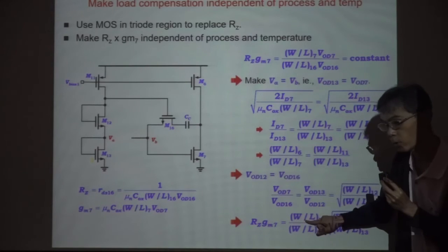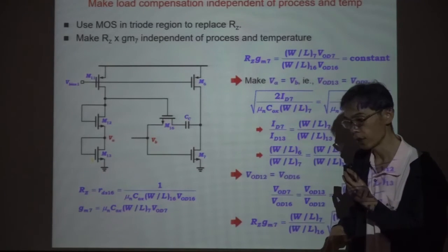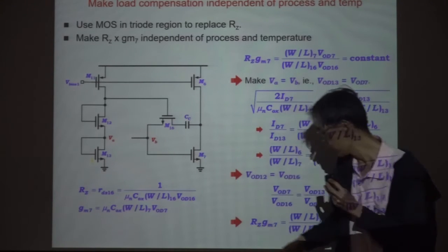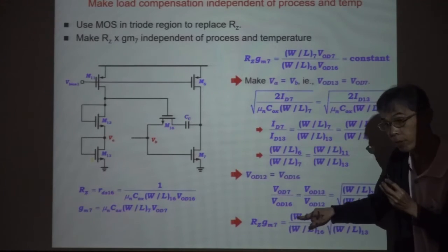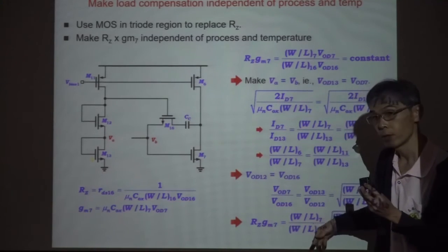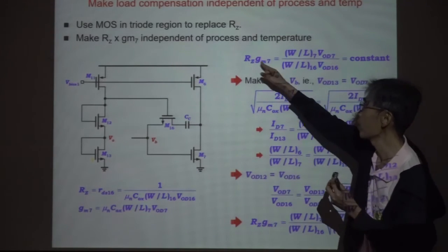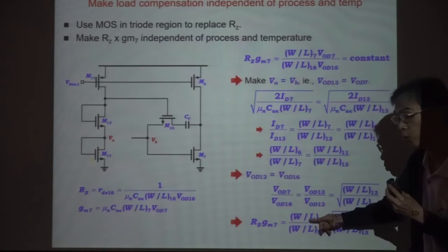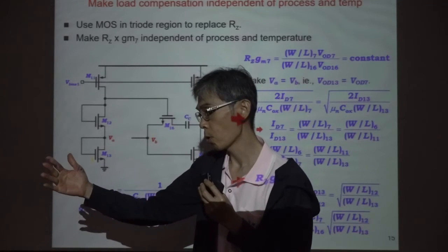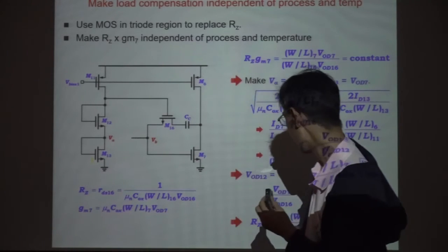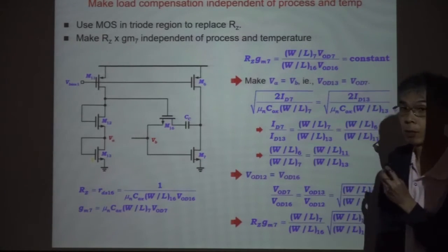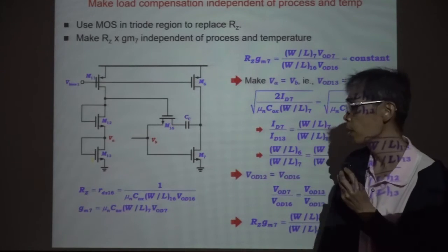Yes. See, during the CMOS fabrication process, we have the photo mask. If there is an alignment error, we will make the same error for all of them, so the alignment errors cancel out each other. So process error is eliminated, and for temperature, heat expansion or cold shrinkage, they will expand and shrink all together. So we can avoid temperature dependence. Okay, do you understand? Next.